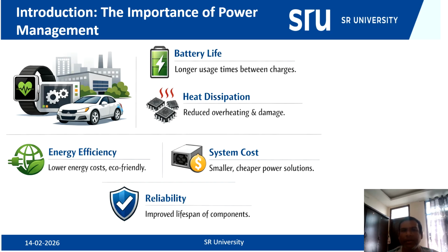High power consumption leads to increased heat generation within electronic components. Excessive heat can degrade the performance, reduce the reliability and even cause permanent damage to the devices. Managing power efficiently helps keep the operating temperature low and avoids the need for bulky or expensive cooling solutions like heat sinks or any external cooler.